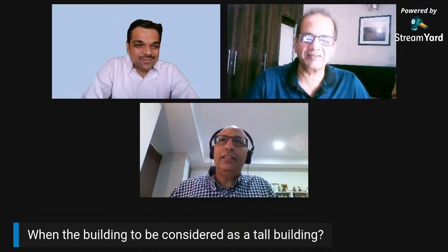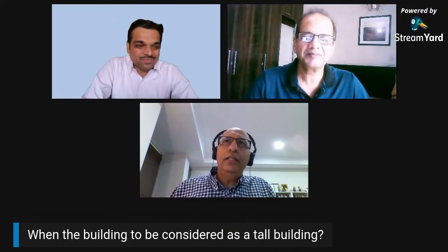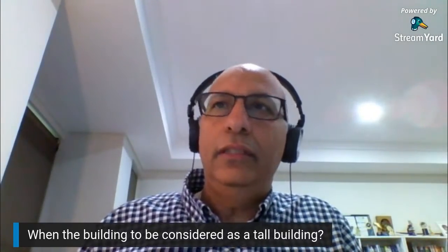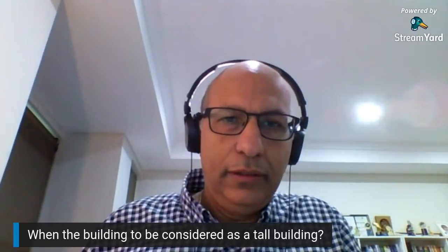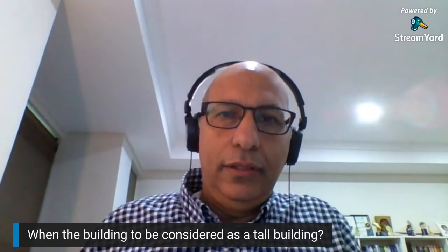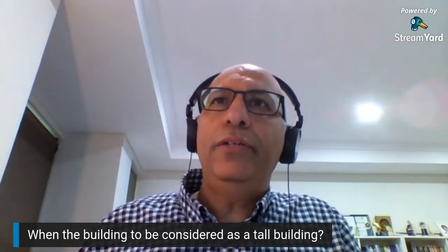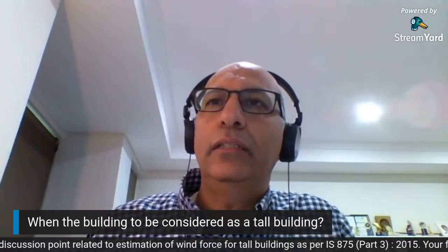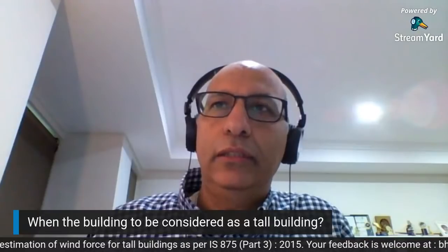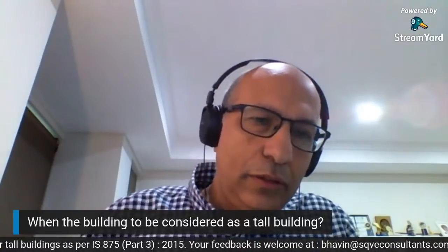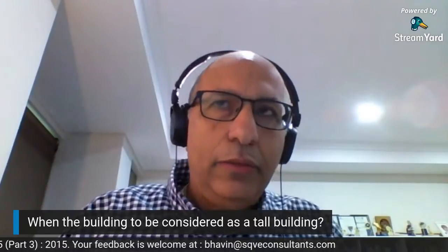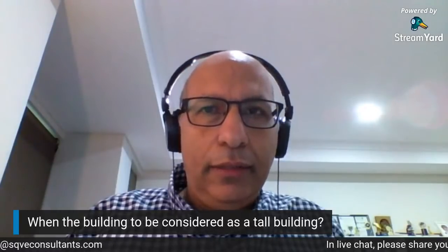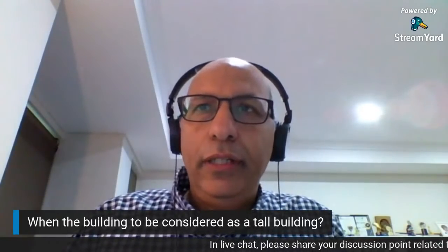Dr. Tony, maybe I can add. In IS 16700, section 6.2, a tall building is defined as any building above 50 meters, which is consistent with what Dr. Gupta mentioned: anything with a frequency less than 1 hertz, and that is essentially the same thing.